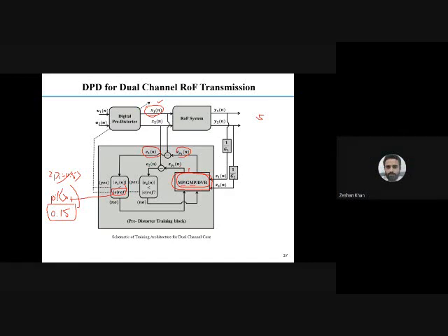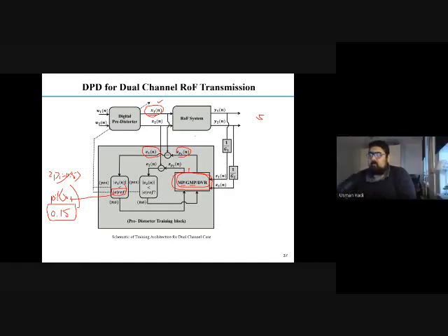Okay. So even if you don't do it, there is no effect because you are actually... For example, if you have a response of signal something like this and it is centered at 0, maybe if you don't do the signal adjustment, it will have some offset. So in order to remove the offset in magnitude, you bring it back by using the gain adjustment amplifiers.